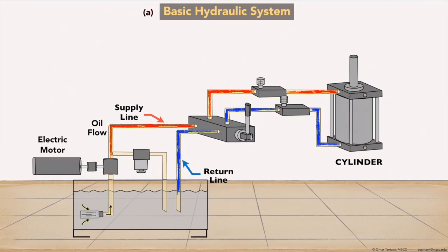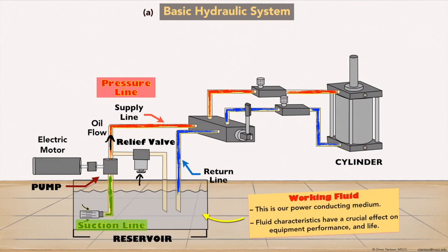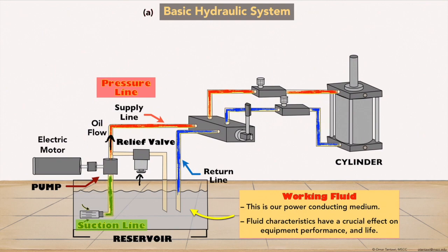This is a basic hydraulic system where each unit can be divided into three subunits. So the power unit contains a pump unit. It takes the oil from the suction line and supplies the system with pressurized oil. The amount of oil can be adjustable. A pressure protection unit protects the system from high buildup pressure. This can be adjusted. A tank unit contains the working fluid and it cools, measures, and filters the oil and smooths the oil flow into a laminar flow.